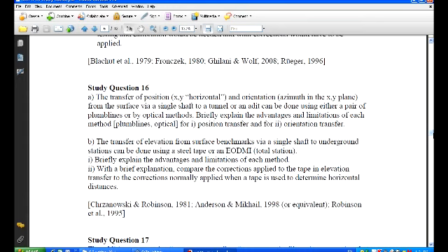And then there's a bit of difficulty about getting the things lined up properly, which is usually overcome by having a special instrument where there's an actual little target mounted on the inside of the telescope that would allow the other instrument to focus onto it to get the proper centering.